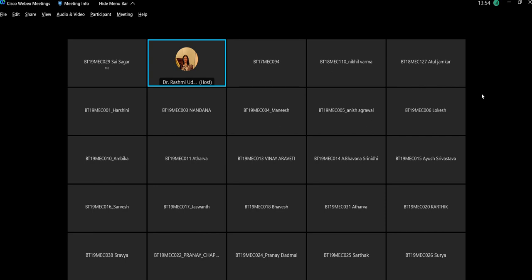Grinding, rubbing, vibration, noise. Yes, this is the answer I am looking for. You know there are vibrations, you know that the engagement is jerky because it will come with a crackling sound, where the teeth are parallel to the axis of the shaft.